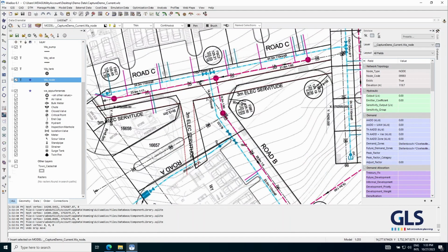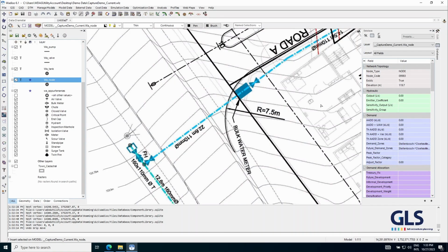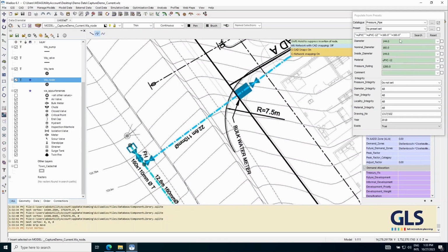So for the additional information of 110 pipes, I will again choose there. Your last entries will be remembered. What you can do is reset all of the search, and I know UPVC 12 is correct, so I'm just going to tick that box. So when I do a reset, that value will not be cleared. And again, in terms of nominal diameter, we can search for 110 because we know that is the value. Again, all green, all of this information will stay the same.